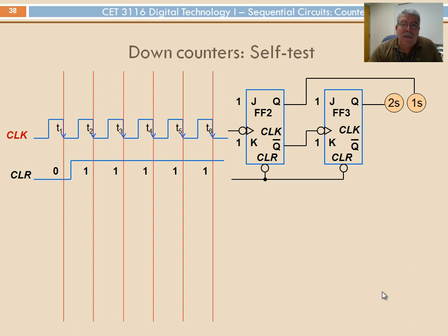Ideally, you should take your time and think what would be the output signal for both flip-flops, and just follow exactly what we did at the beginning. The only thing is that we start with 0 instead of 1. We're doing a clear. So Q will start with 0 for both, and Q0 will then be 1. So that pretty much doesn't change much.